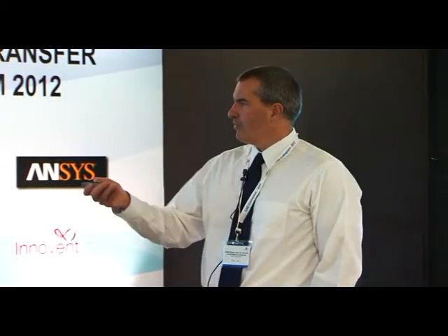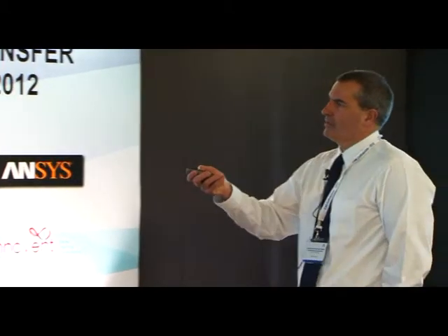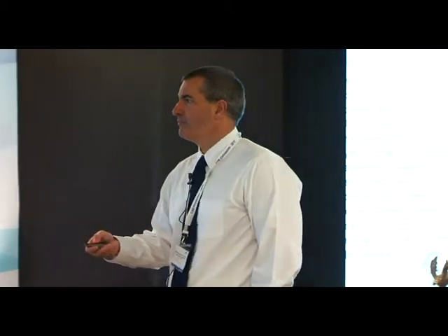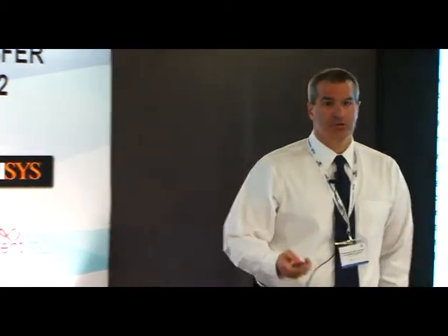And just to give you an idea where we're at, this is an old graph, but a good graph, where you're looking at cooling technology versus turbine inlet temperature. As that turbine inlet temperature goes up, you can go from a solid blade, like you would see in a low pressure turbine, to a convectively cooled blade, to both forms of active cooling, which is internal convective cooling and film cooling on the external part. And as noted here, you go to advanced cooling when you get up to the current modern turbine inlet temperature levels. That's what I want to talk about: how do we actually develop models for the film cooling of these things?